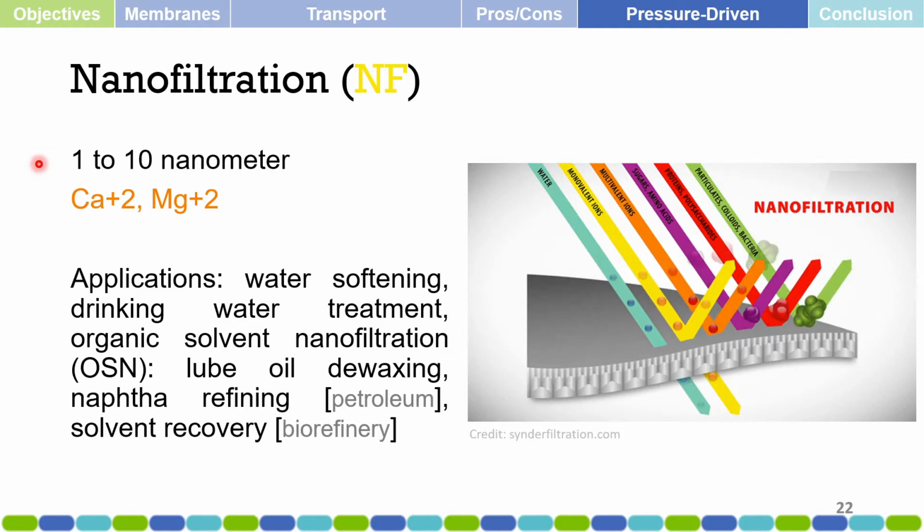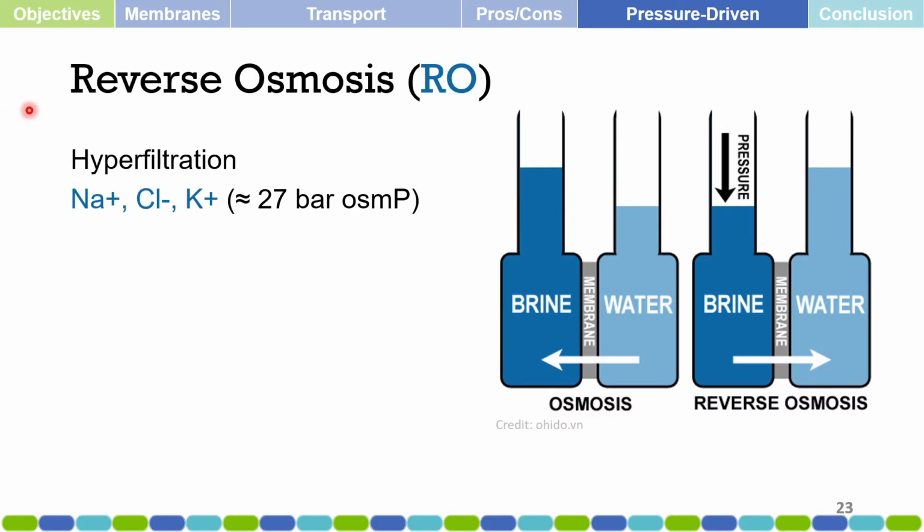As compared to the ultrafiltration and microfiltration processes, it has a very, very small size of components which it can reject. These nanofiltration membranes are now employing dense membranes, including porous membranes. That's the difference between nanofiltration and the other types of membrane process we discussed earlier.